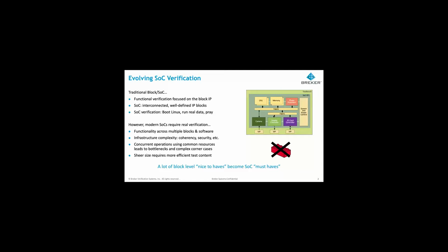In the past, traditional SoC verification has been focused on just making sure that SoC blocks are fully interconnected and working properly, and the functional verification of a system has been targeted towards the block level and making sure the individual blocks are functioning correctly. And I think this is almost a hangover from the days 20, 25 years ago, where you had a processor and a number of chips on a board, and the chips would do the functionality, and then you get the whole thing working afterwards. So verification would consist of booting Linux, running real data, and just making sure the SoC was basically functioning.